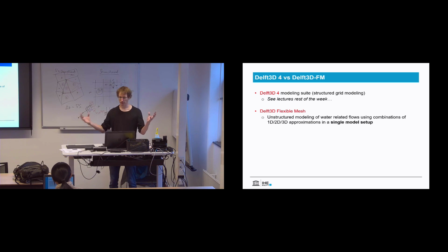So you don't have to make separate grids or models, you don't have to do domain decomposition, none of that sort of thing. Okay, so the big advantage is you make your model once and then you can easily adapt it. So you don't have to redo the entire model, because everything is basically in geographical coordinates. So you could just delete the entire grid, remake a new grid, and for example, all your boundary conditions would still be valid. Yeah. So that is very cheap.